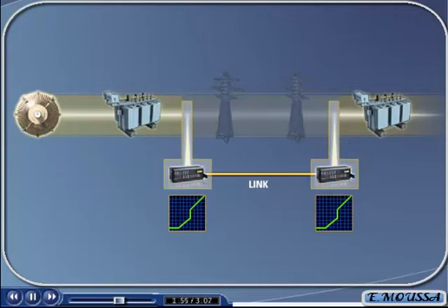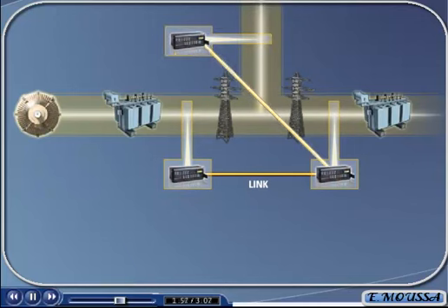The L90 relays support both 2 and 3 terminal configurations. The relays in a 3-terminal configuration will behave in the same fashion as the 2-terminal configuration, with each relay making its own decision as to whether it will trip. In this way, all L90 relays are said to act as masters.